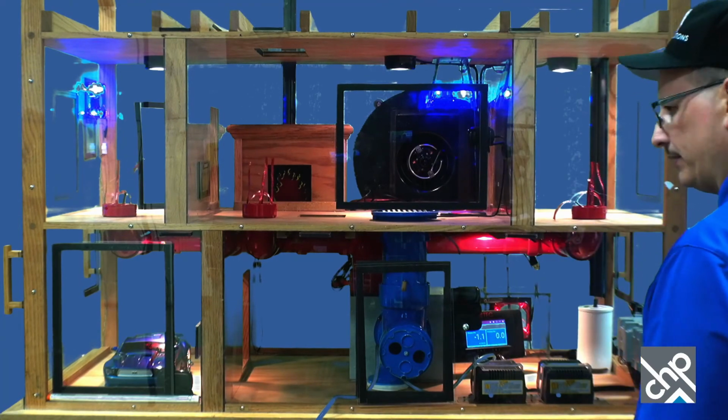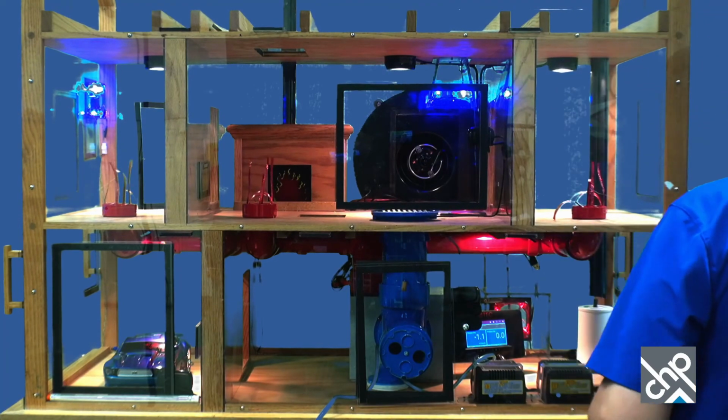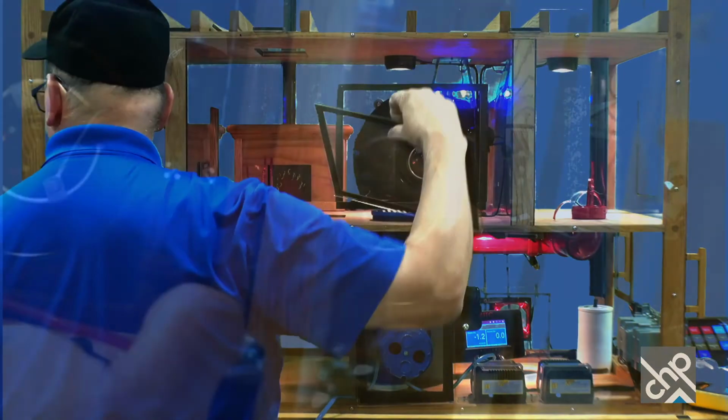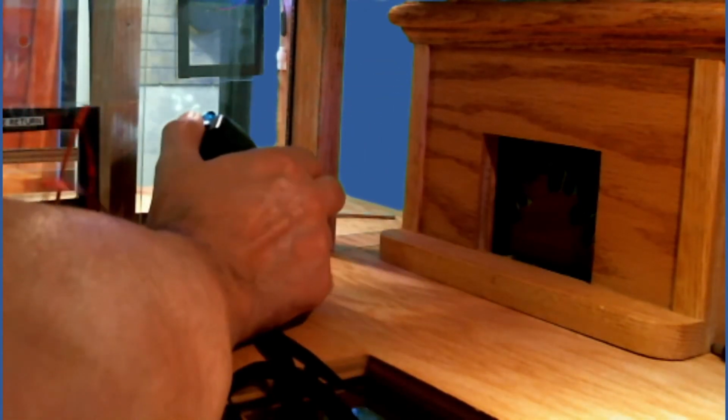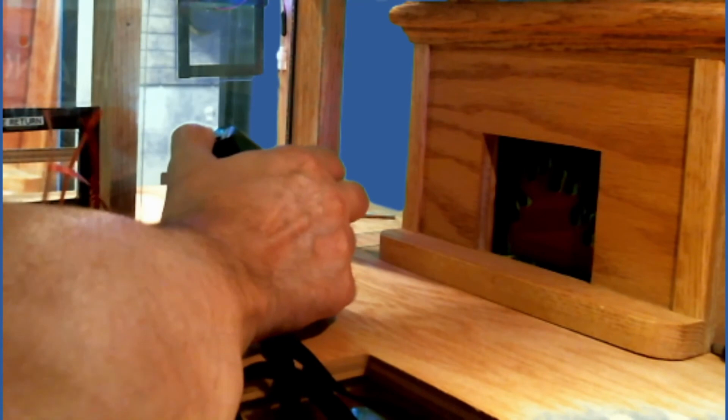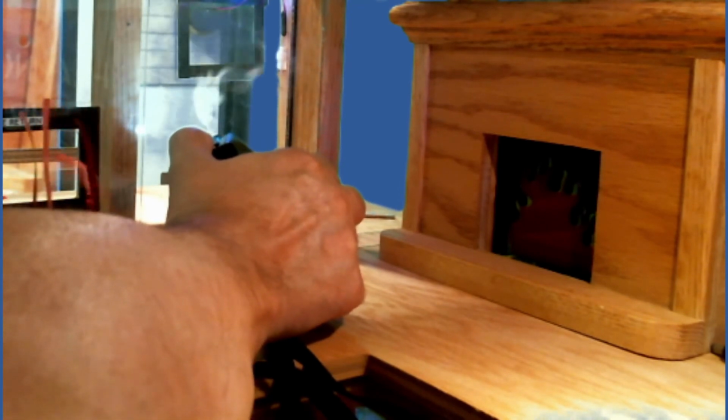So I'll just go through the steps here with a little smoke pencil. And then here it is. And we'll do the bedroom first. You see it's blowing back. So if it's blowing toward me, where I'd be out here where my hand is, I don't want to leave that door closed. All right. And then we'll go over here to the bathroom door again. Go check it. It's actually blowing back into the room as well. So it would be closed too.